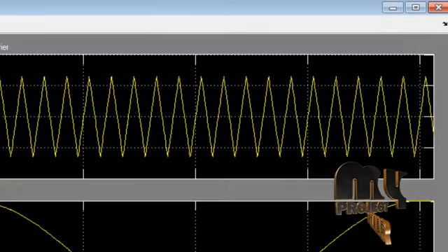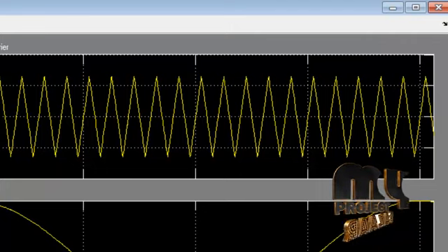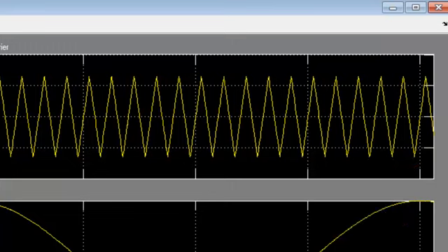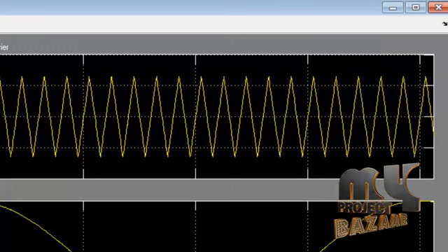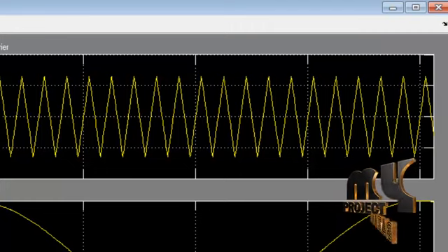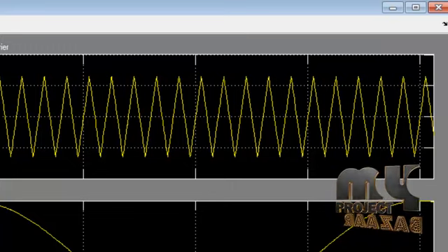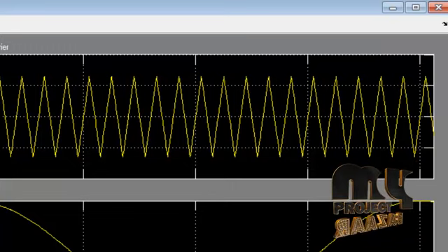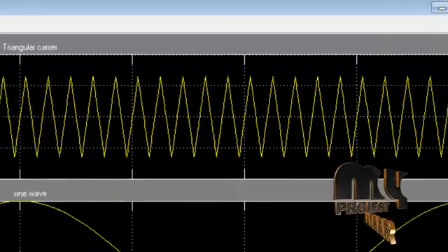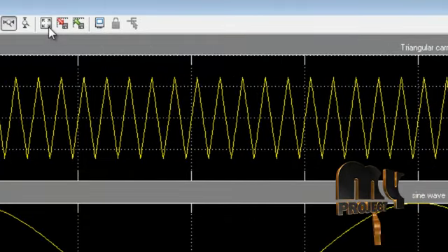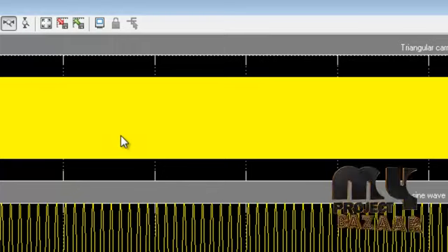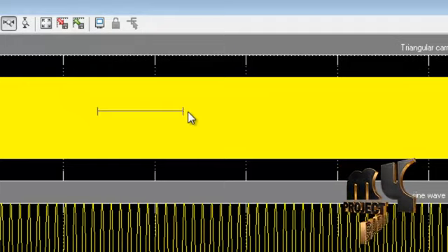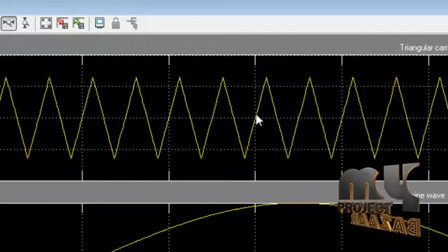This is our sinusoidal pulse width modulation, showing the carrier, the sine wave and the triggering pulses. These are three waveforms in a single scope. First we can see the triangular carrier, which is compared with the sinusoidal wave, and next the sinusoidal wave and the triggering pulses. This produces the triggering pulses, and then the third scope. There is some transient variation here, but it is not a problem. Zooming in on the x-axis, this is our proper wave.